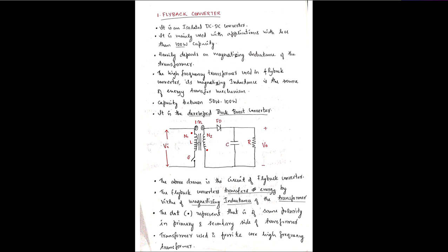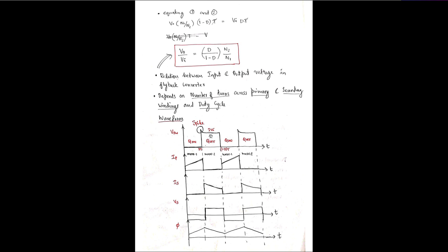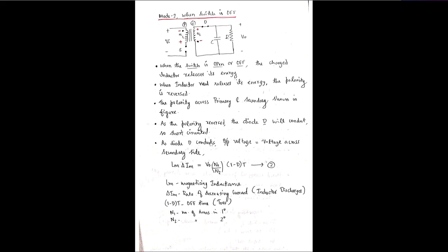Plus the already existing Vi input voltage, so across the switch it will be 2 Vi voltage. The spike I have shown there is because of the presence of the inductor. So during off time, the voltage across the switch will be 2 Vi. How is that 2 Vi coming?